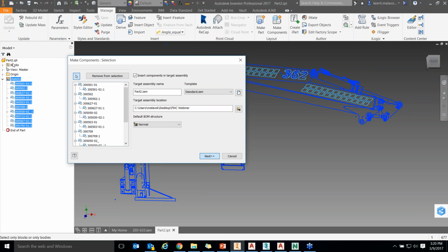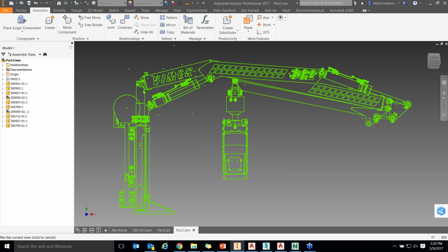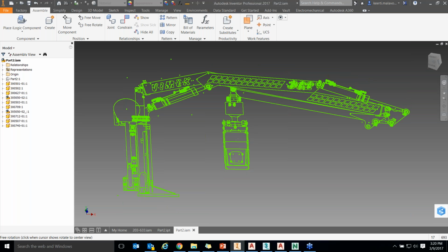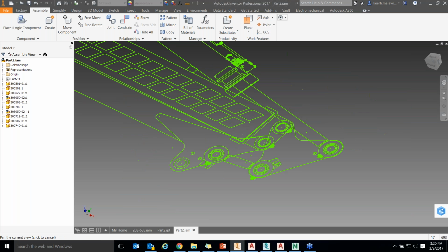And if you can see here, now it has created an assembly file. So .iam is the assembly file extension for Inventor. So it has created a complete assembly file. So we were talking about the concept part of it. The first concept is to see whether the overall kinematics of this particular linking mechanism works or not, based on the design we had. So it has got a lot of different types of constraint mechanism,